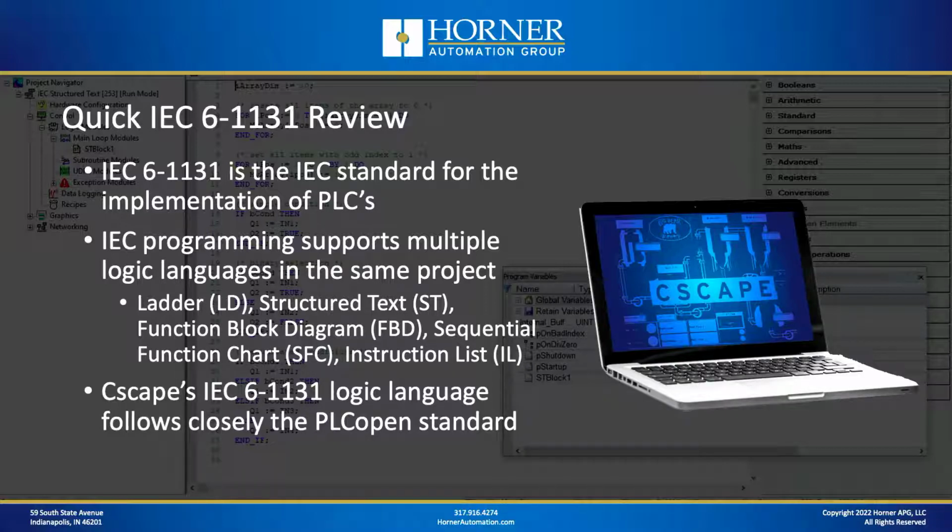Now, one thing to keep in mind is that Cscape's IEC 61131 implementation follows closely the PLC Open standard. So for those of you who joined us last week, you may have noticed that the ladder editing within the IEC package is not exactly the same as advanced ladder, and that's because it follows the standard a little more closely while in that environment.